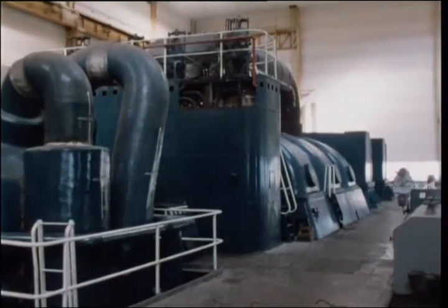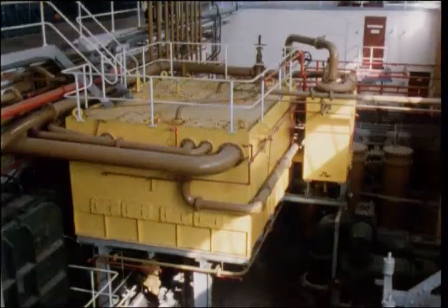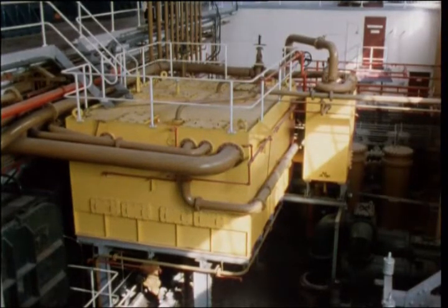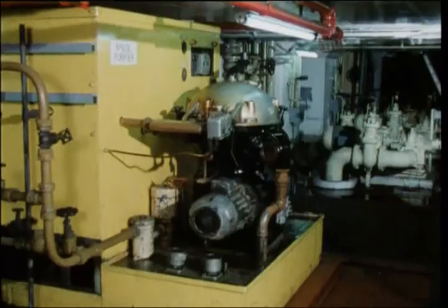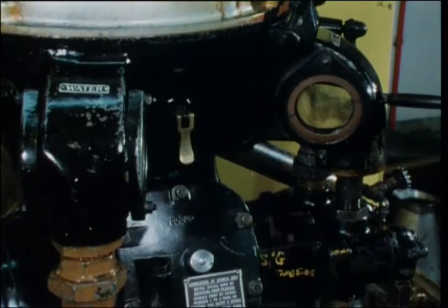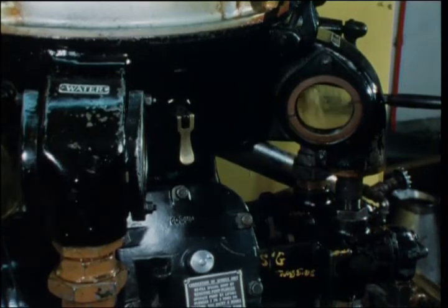In a generating station, the quantity of oil needed to lubricate a turbine is very large. Some steam always leaks into the oil, and most of the condensed water is removed by centrifuging. But inhibitors have to be used in the oil to prevent corrosion of metals from water remaining in the system.